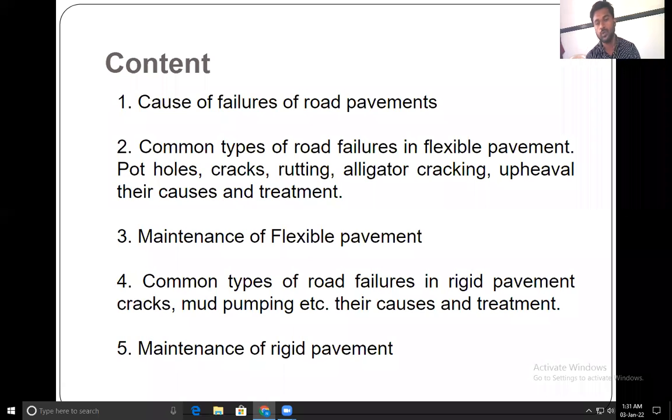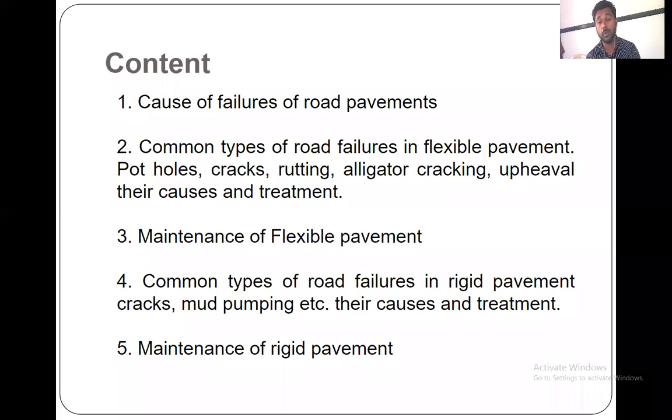Then the common types of road failure in the rigid pavement are cracks and mud pumping. Okay, this mud pumping is nothing but the slurry of mud that comes out from the joints due to heavy load. So why this happens, how to prevent it, and how to go for the maintenance of it, all these things we need to study in this chapter. Okay, so we will see one by one.